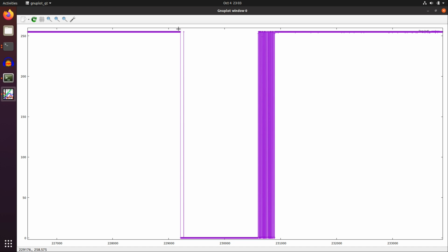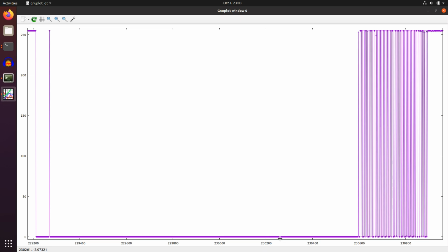Alright, so we can zoom even further into this, and you can see it becomes faster. So here's our line idling high, and here you can see the reset pulse. Sometimes there is a glitch, so this point here, for instance, is a very short glitch that is probably not there on the line. That's because this is just a small ATmega oscilloscope, so these things tend to happen. Just ignore them. And here we see the data transfer actually. So this is even more interesting.